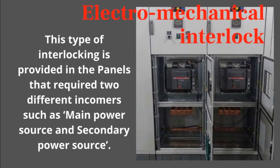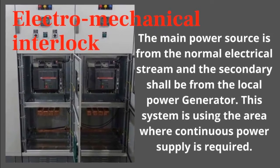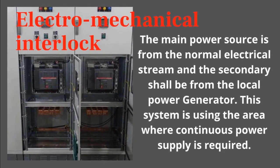Electro-mechanical interlock. This type of interlocking is provided in panels that require 2 different incomers, such as a main power source and a secondary power source. The main power source is from the normal electrical supply and the secondary shall be from the local power generator. The system is used in buildings where continuous power supply is required.